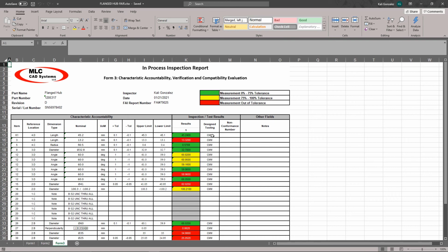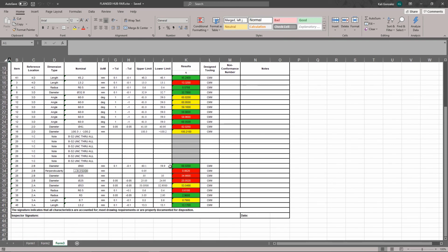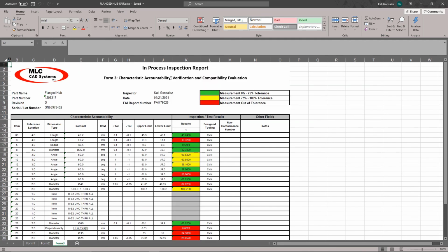The Excel file that results is going to contain only the items that were set to yes for my in-process report. This is by far the simplest way to export information when you only want a certain subset. Now, you do need some type of variable or column information like we set up to drive this, but once it is set up, all you have to do is worry about a filter.